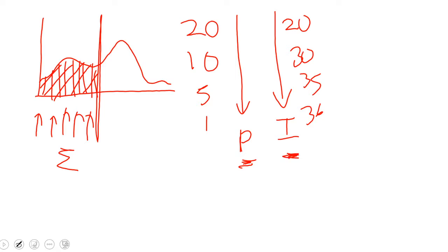So what we would have is, even towards the end, a significantly higher value that can significantly apply to the change that is needed. The proportional component of the error will reduce, but the integration of the error values will increase.